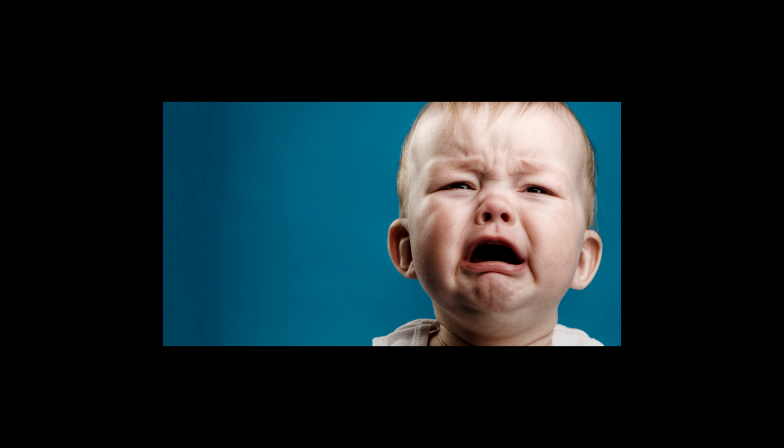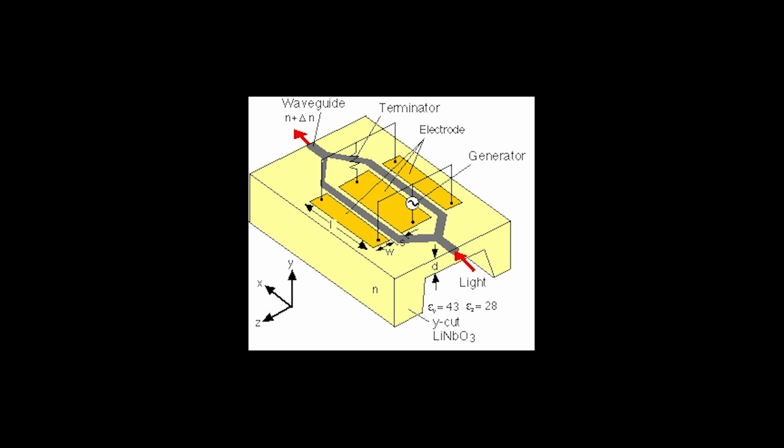Being able to control the path length with tens of microns accuracy is incredibly difficult. Also, the alignment is so precise that our graph may be shifted due to environmental factors shifting the system in between measurements. This type of interferometer was and still is used for external modulation of optical communication systems. They minimize the effect of dispersion, which is crucial for such systems.